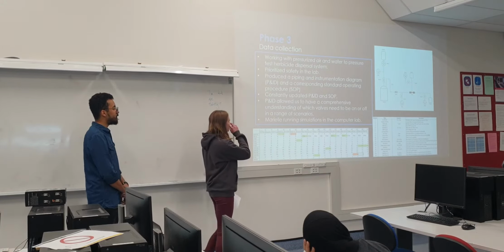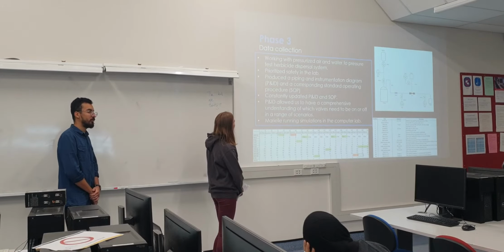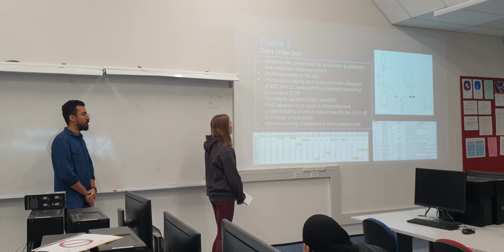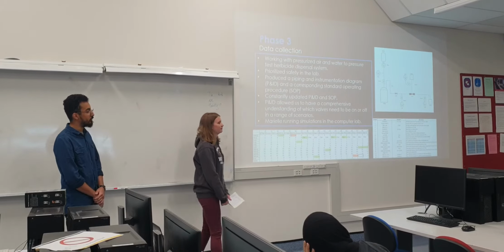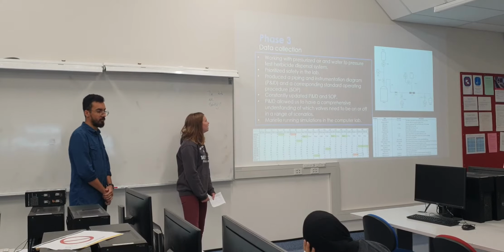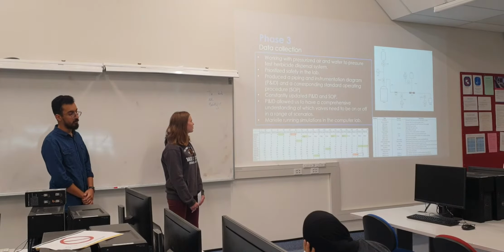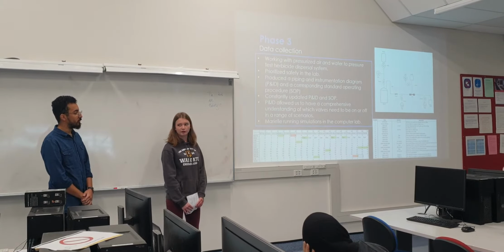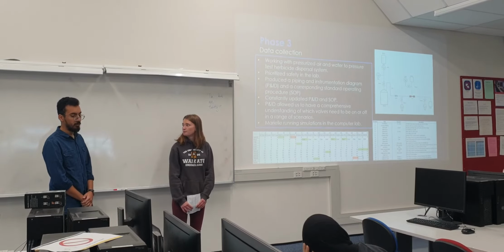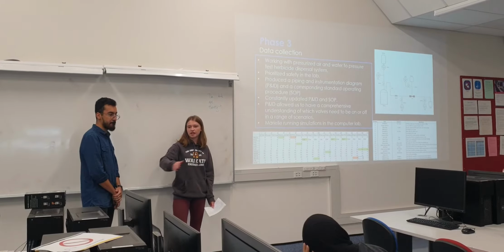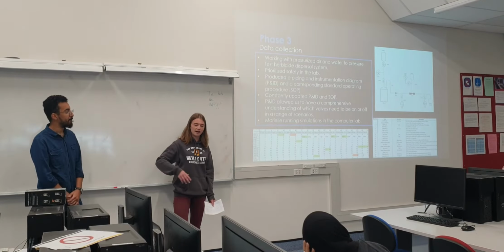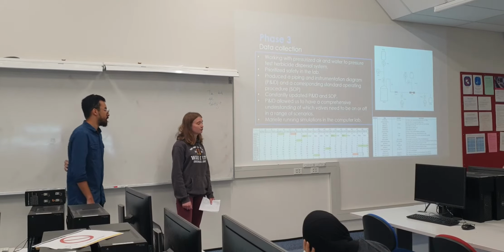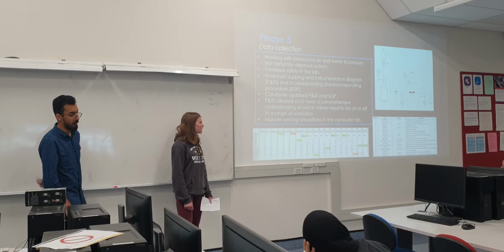Data collection is what we mainly did in the lab. Effectively, we were just pressure testing the system that we had. We put a high priority on safety, putting time into creating P&IDs and standard operating procedures, or SOPs, and constantly updating those, making sure the team's really comfortable with them, and knowing what valves need to be switched off in case of an emergency, because we were working with highly pressurized water and air, which can go wrong pretty quickly if you're not careful.